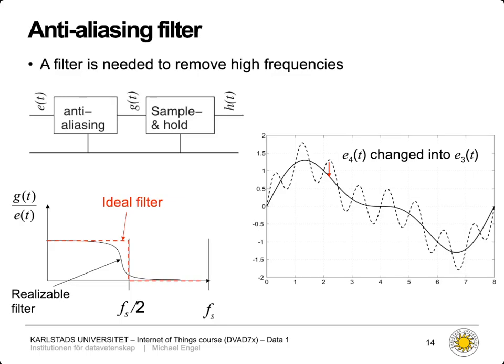So they should be transferred to the right-hand side of the anti-aliasing filter undisturbed. And everything above should have an amplitude of 0. So essentially, we mute our audio level, for example, down to 0 for every frequency that's higher than or equal to half our sampling rate.